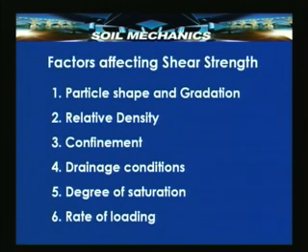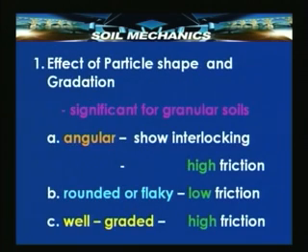The first 3 factors therefore are best applied to coarse grained soils, whereas the next 3 aspects dealing with drainage, the degree of saturation or relative rate of loading compared to the relative rate of drainage, all these things are specifically applicable to fine grained soils. Let us take a look at what the effects of these parameters are. Effect of particle shape and gradation, significant only for granular soils.